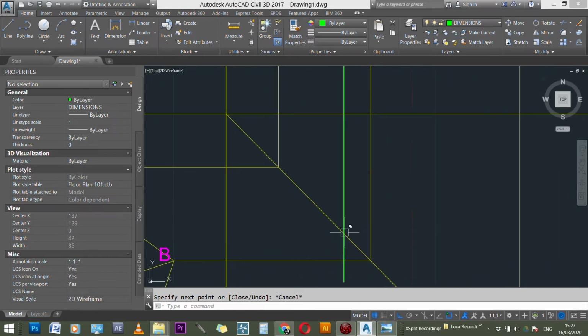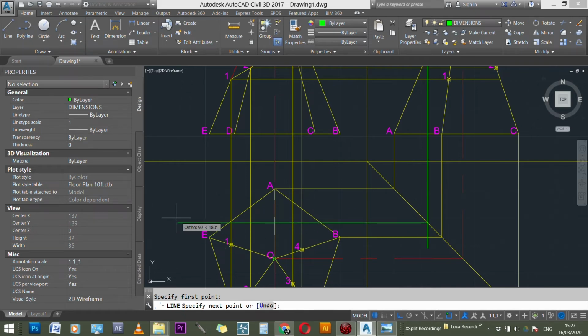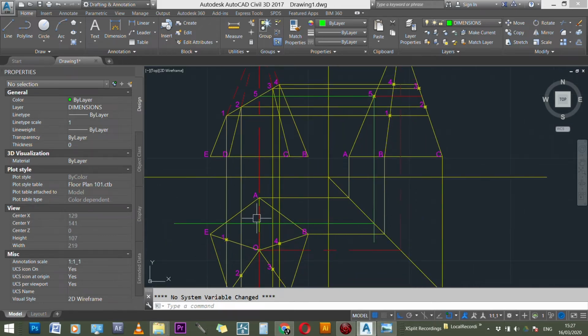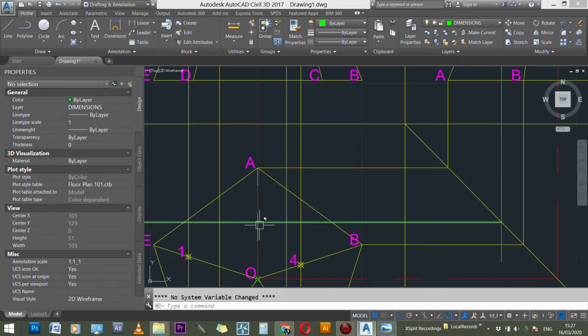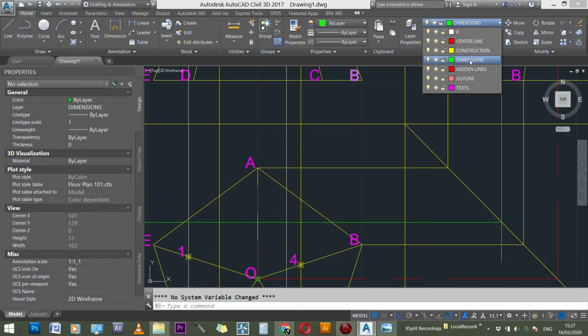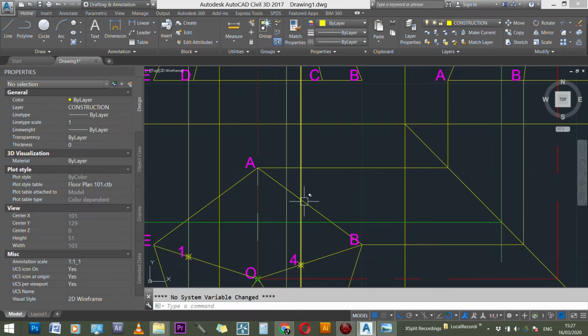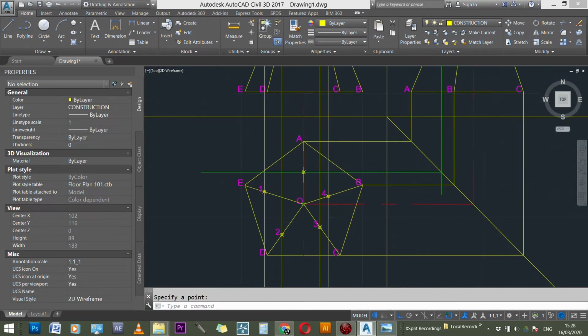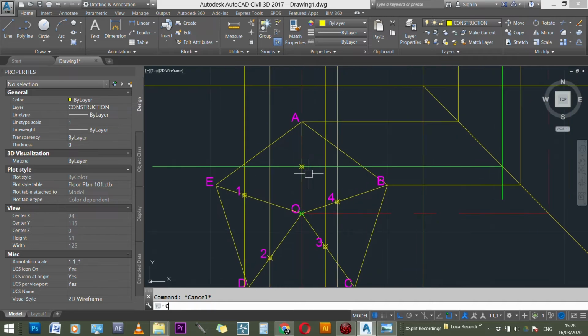It hits the information line here, create a 90 degree, and then we bring it right across. Because 5 was on the A line, we find A and where 5 cuts the A line, and at that point is where we are going to connect this whole thing. So that's my 0.5 there, and I'm just going to place in 5.